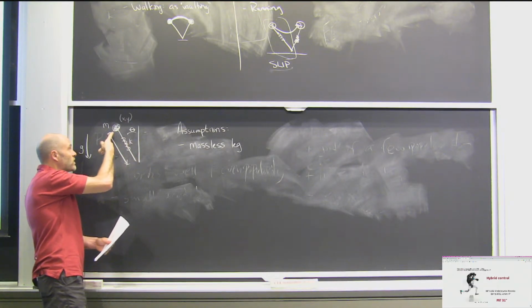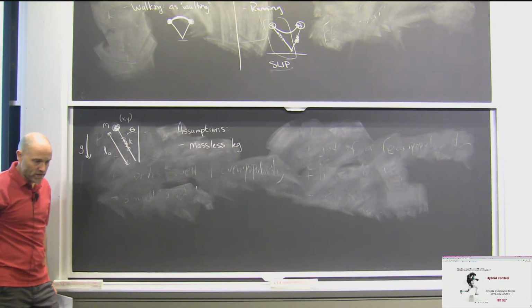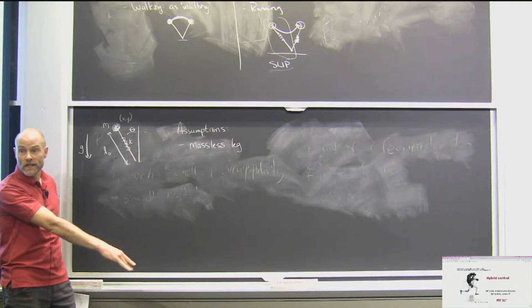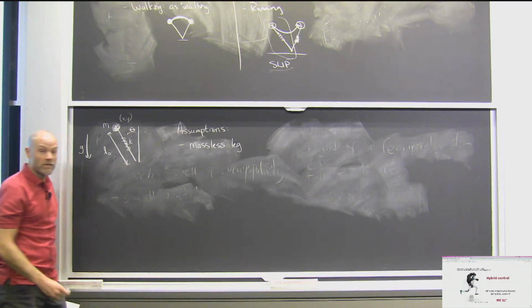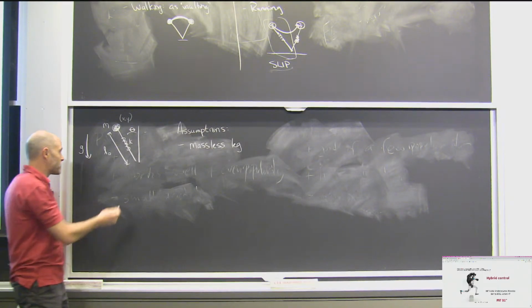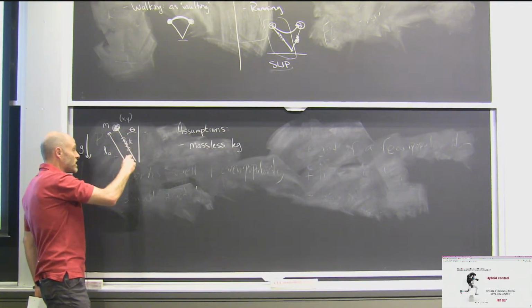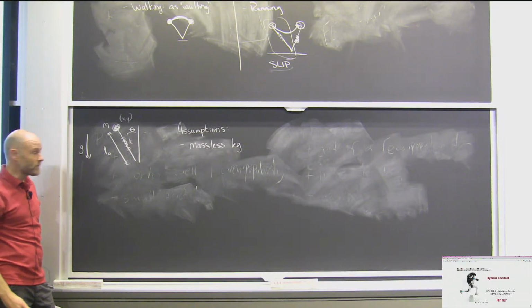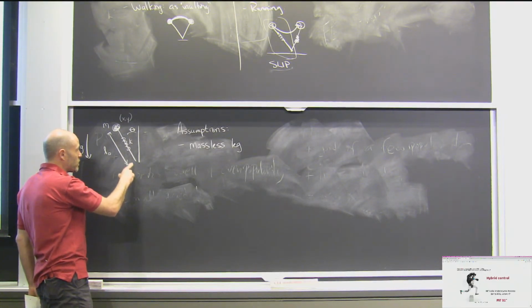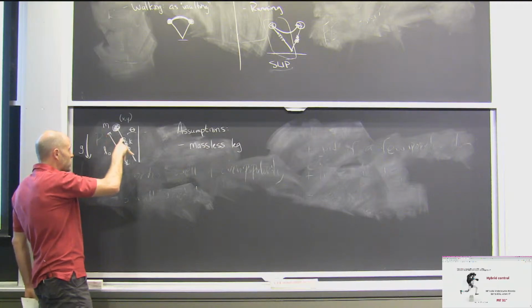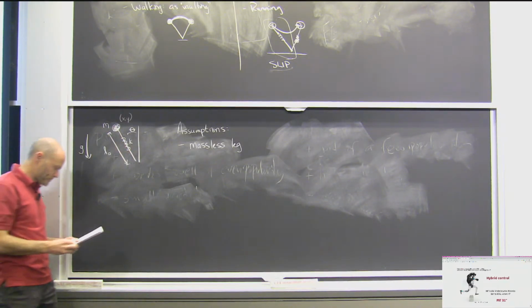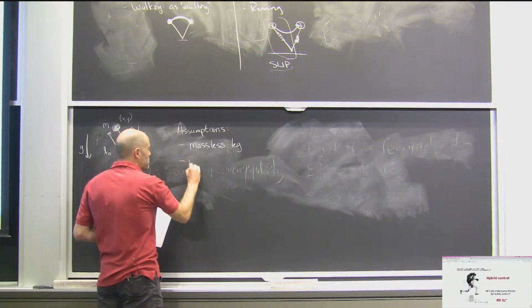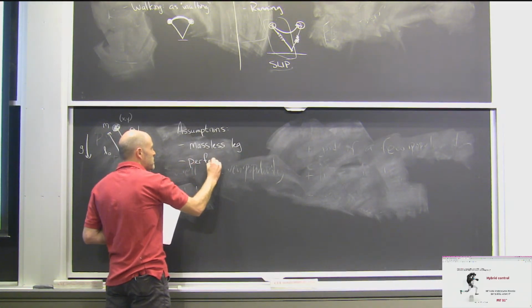So therefore, once I'm in the air, I can basically instantaneously change my leg angle to whatever angle I want. Okay, and in fact, my control input is going to be abstracted to be just the orientation of the leg. Okay, but we'll assume a massless leg, and that when I swing this mass, it has no effect on my center of mass dynamics.